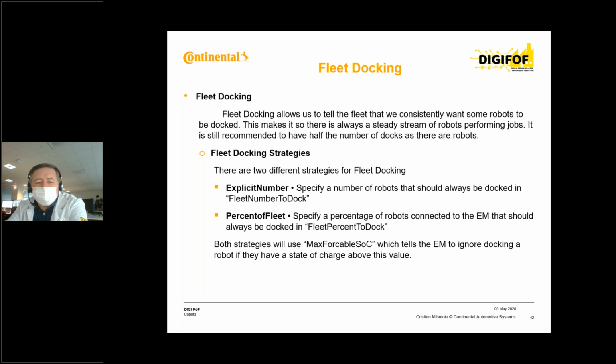We can have some strategies. We can say a specific number of AGVs to go to the dock stations, or we can say a percentage of the fleet, depending on the situation that we have on the shop floor. Usually, we call to dock a specific number of AGVs because mainly we dock them for preventive maintenance and also for software updates. Percent of the fleet to dock, we don't use in our situation.